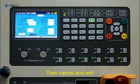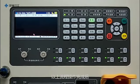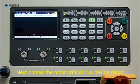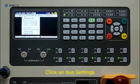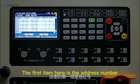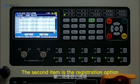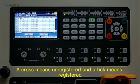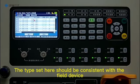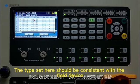Then cancel and exit. Next comes the most critical bus device setup. Click on Bus Settings. Enter the detector module settings. The first item here is the address number. The second item is the registration option. A cross means unregistered and a tick means registered. The third and fourth items are type settings. The type set here should be consistent with the field device.